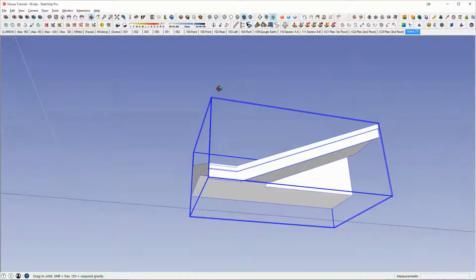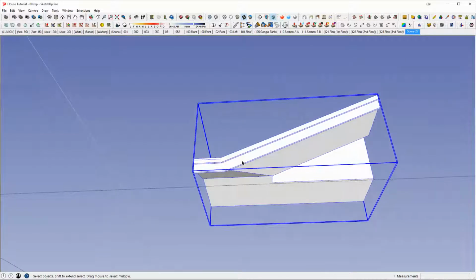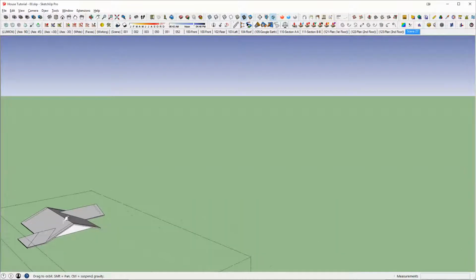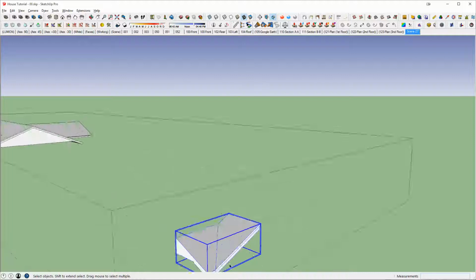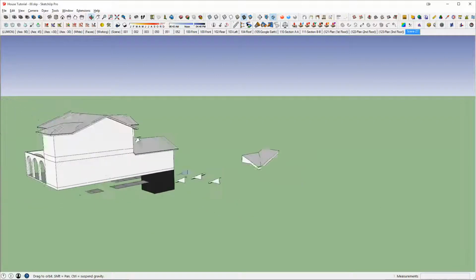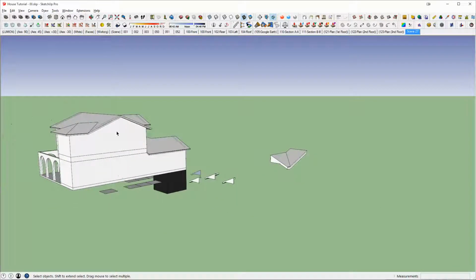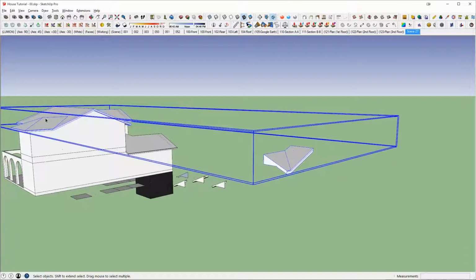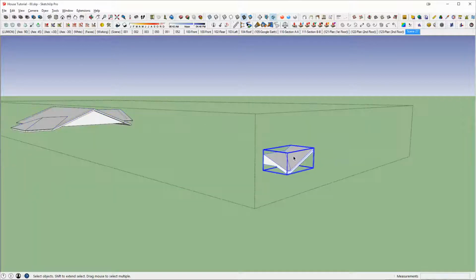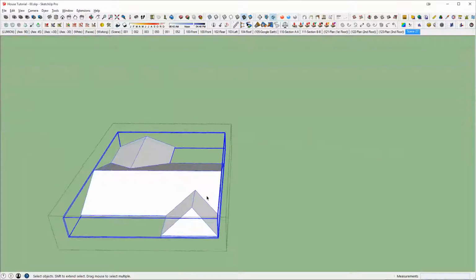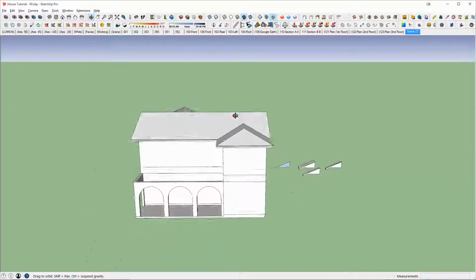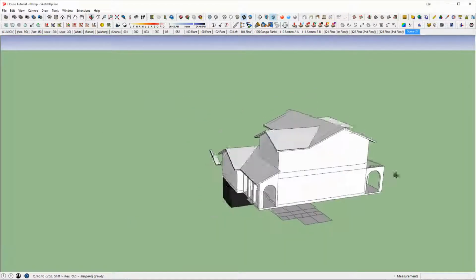Here's a jig that is showing you exactly how to do a gable to a hip. And so next time we have this condition in another house, maybe this is a model house of 4, 5, or 6 houses we're doing, and we're going to do a similar style on another house, so we're going to have the same condition. Here you go. Here's this piece. You just build it and plop it in as you need to. So that's a great way to continue creating jigs that work in your favor.